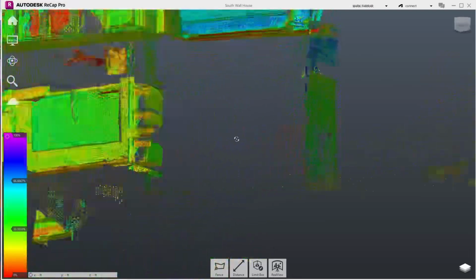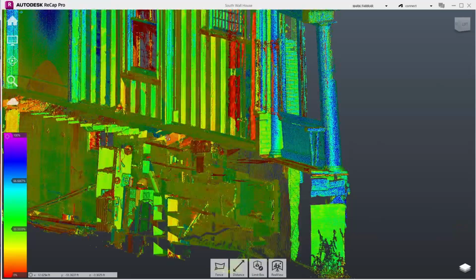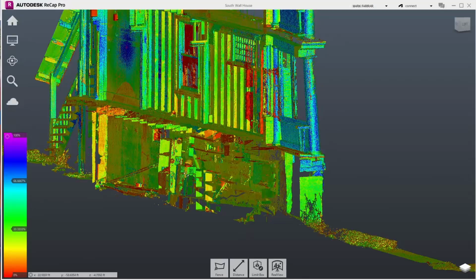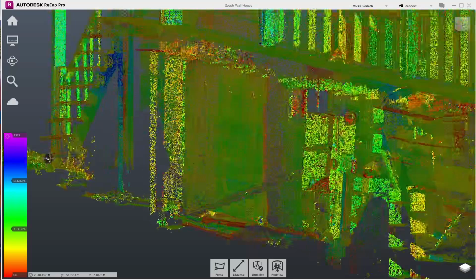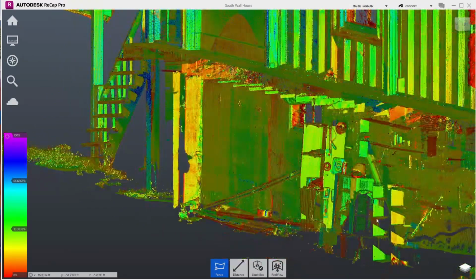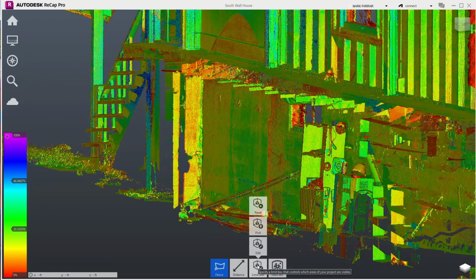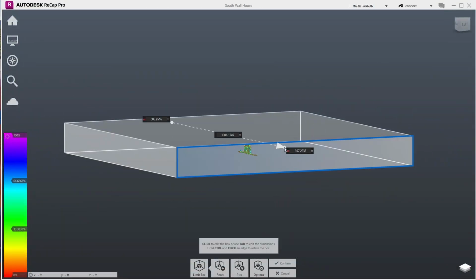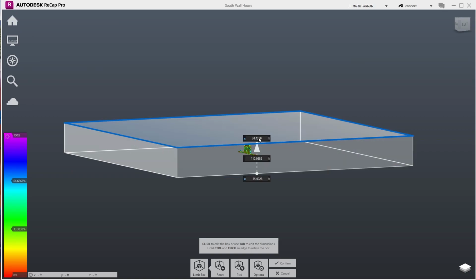But to get to items like these, if I've determined that I want to get rid of them, I can use a limit box and narrow down my selectable area temporarily without changing the limit box permanently by just not saving whatever's happening right then and there. Now, I just happen to be sitting in an angle where I can see a whole lot of plant stuff. Just going to get rid of it while I'm sitting there. So what I'm going to do is hit limit box. It's going to zoom me way out. Hit edit.